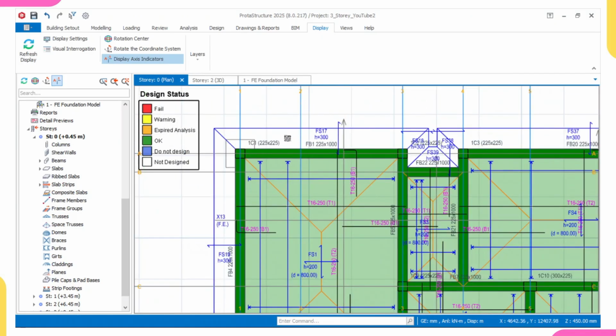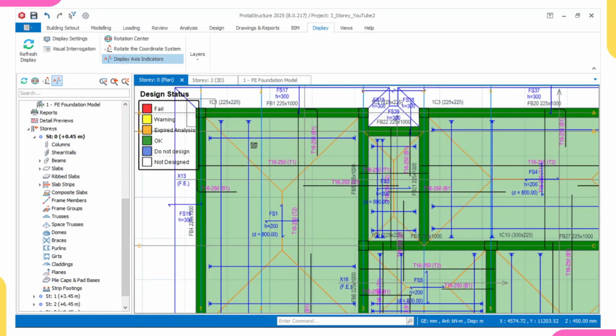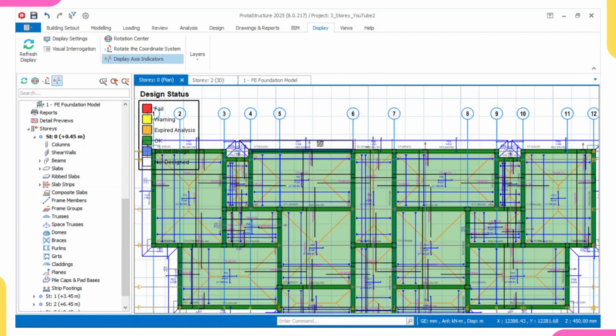So I did not do this design. But normally, as we were to do the design, I'm sure that you can do it. Once it comes to slab strip, you go to finite element and then you use the boundary condition for cantilever. But in this case now, I will just do the interactive design of a few of these beams, not all of them.